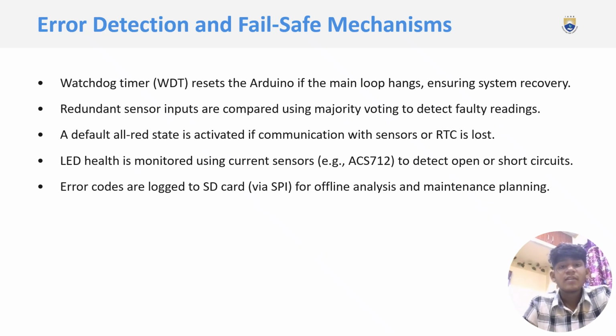Error detection and failsafe mechanisms. Watchdog timer, WDT, resets the Arduino if the main loop stalls, ensuring system recovery. LED health is monitored using current sensors to detect open or short circuits.